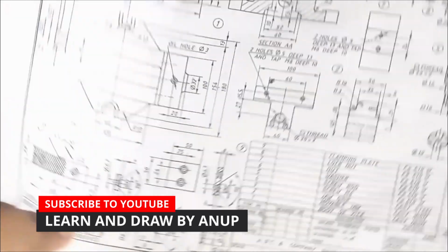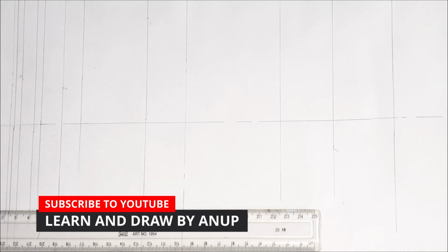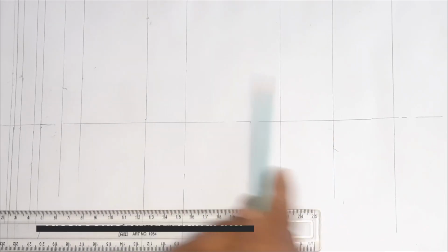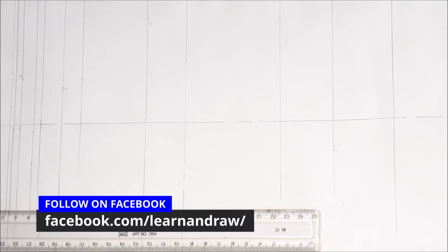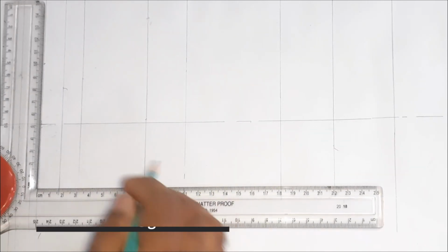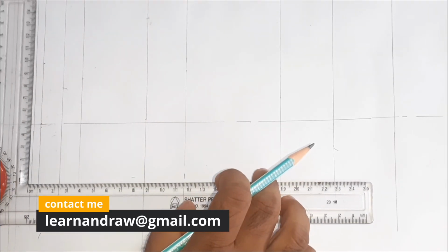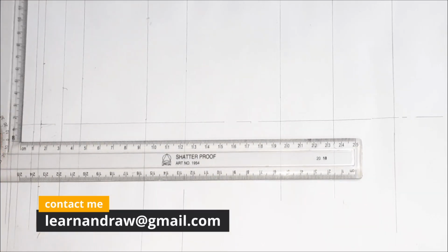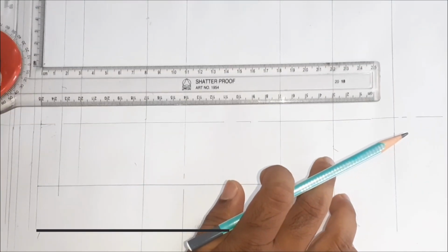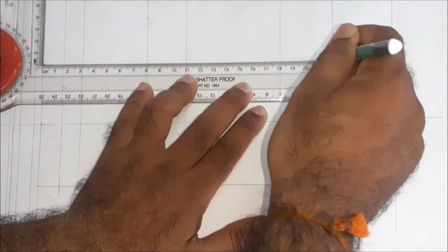To draw the outer rectangle, we will take these projection lines. This is one projection line, and next, this is the other. These two are the outer lines of the vice. Then on these projection lines we have to mark the distance of 50 and 50 mm and complete this rectangle. On this projection line I am marking 50 mm, and here at the bottom also I am marking 50 mm. Let's complete this rectangle. Here we have drawn the outer rectangle.